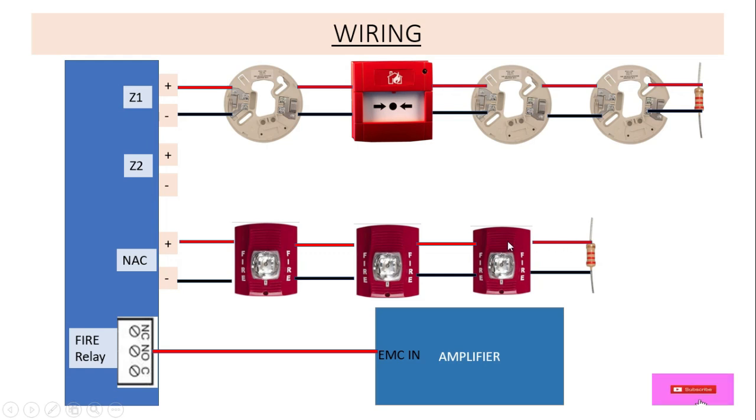Now another is integration. There are fire relays, fault relays, and supervisory relays. In case of fire, there is a PA, meaning an amplifier, a public announcing system for emergencies. We can use its contact to operate this amplifier.